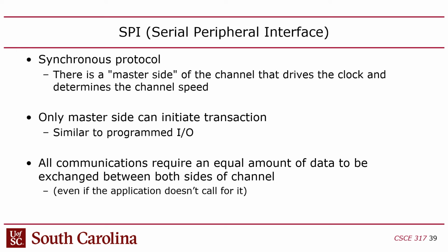So SPI is clearly designed to be used in a sort of programmed I/O style environment where I've got a CPU who's the master and the peripherals are the slaves. They're the ones that you're doing programmed I/O transactions with. Okay, now SPI has some weird quirks to it though.